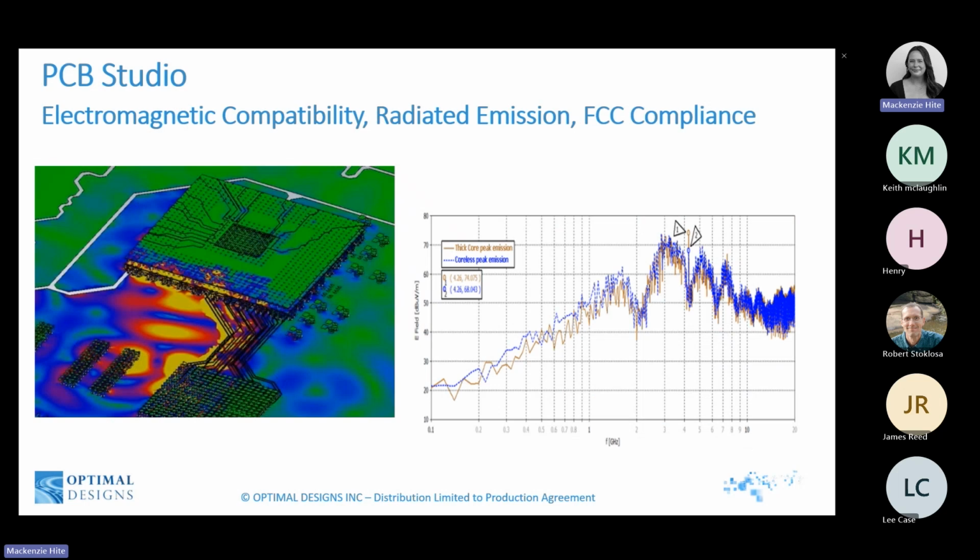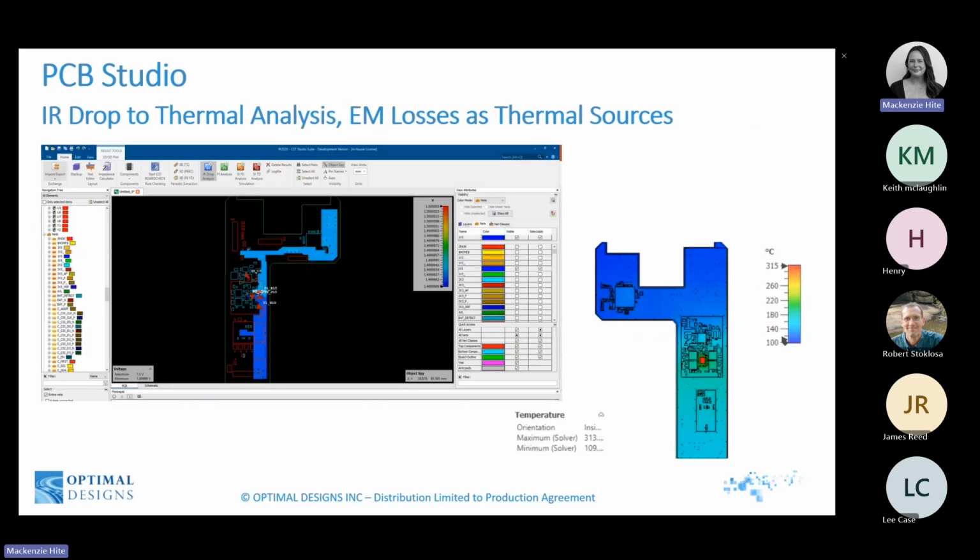Many PCBs have FCC requirements for radiated emissions, which can be computed in CST. This virtual prototype can save time and money before compliance testing. In this example, after the IR drop calculation, the 3D losses can be exported as a heat source for thermal and structural solver co-simulation.